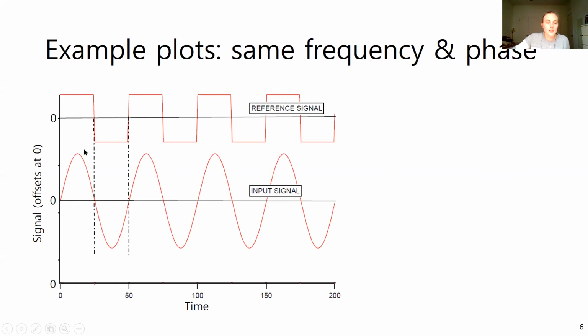So we have a positive signal times a positive signal, negative times a negative, positive times a positive. So we'll get an output that looks like this, an entirely positive signal. So this would be our multiplied signal. This is what the multiplier would be doing, or the multiplier is also called a mixer or demodulator. So the mixer would result in this.